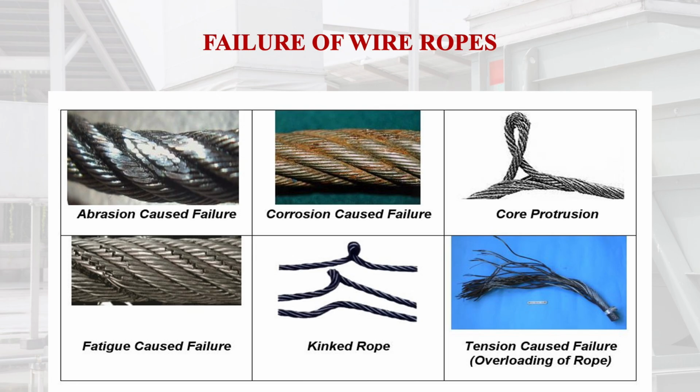The next figure, in the middle of the bottom row, is showing the kinked rope. This kinked rope is also very dangerous because with the passage of time, stress concentration will be there, and the fatigue will further increase the failure possibility of this wire rope.